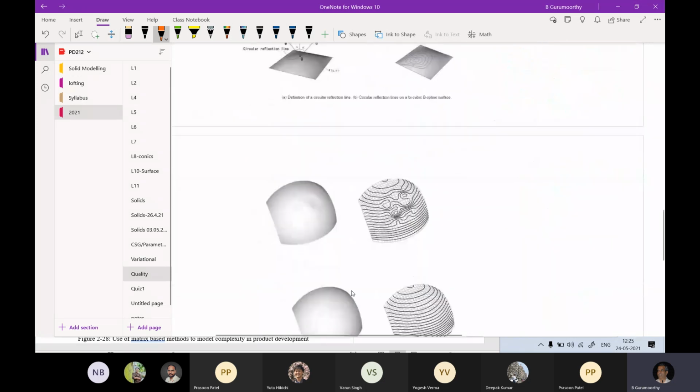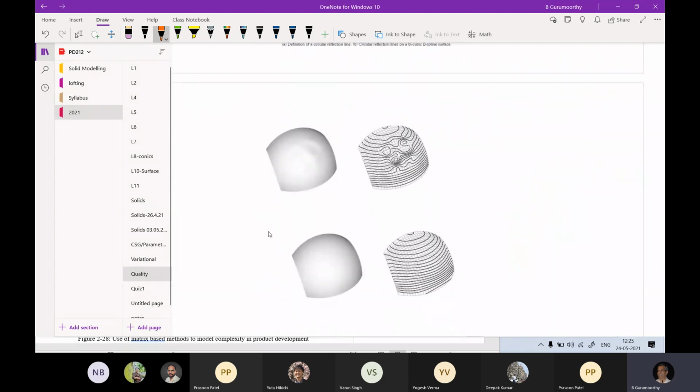You can see the difference here. In a relatively smooth surface, without any undulations, you get these nice circular lines projected onto the surface, depending on where you started from. So maybe the viewpoint is somewhere from here. But here you can see that there are some dents or depressions, which, while smooth in terms of the derivatives, are not good in terms of the quality of the surface.